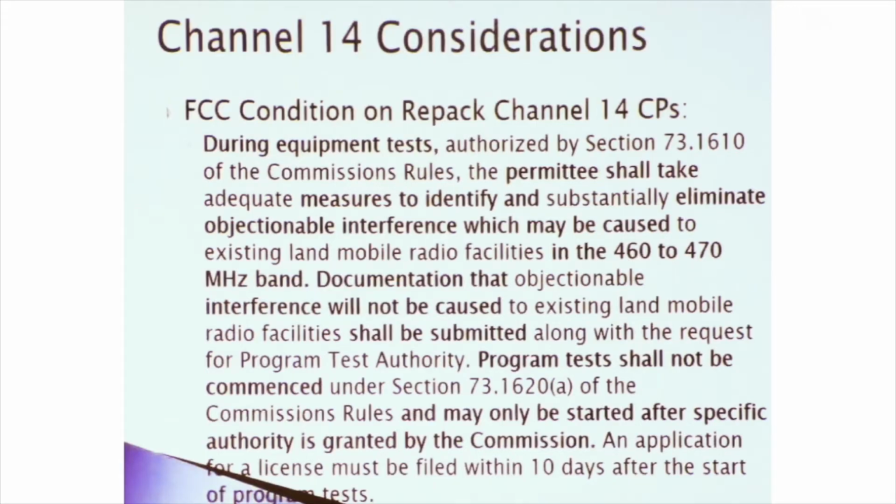To think about what the fundamental characteristics are, the receiver threshold for a 1/4 microvolt is minus 119 dBm. If we have a receiving antenna gain on the order of 6 to 13 dB, which would be typical for land mobile kind of reception, that pushes the threshold down to minus 125 to minus 132 dBm, effectively in the air, if you will. On top of that, there's an FCC mandate to protect land mobile radio service reception.